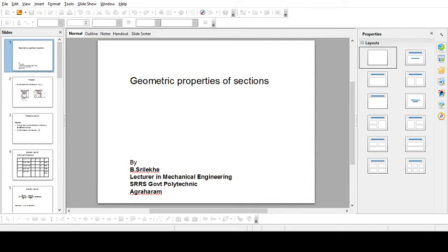Next the horizontal term: it is 30 plus 4r by 3 pi, because it is at a distance of 30 from the y-axis. So 30 plus 4r by 3 pi will give you a value of